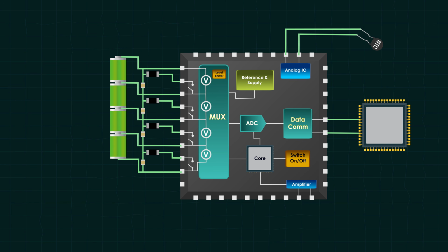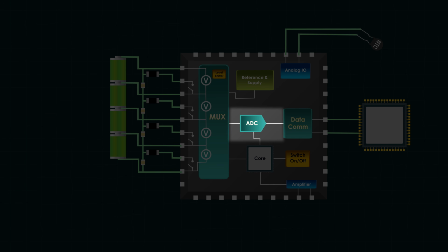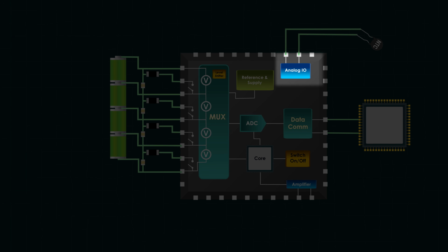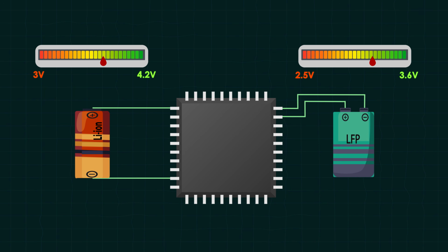In summary, the AFE is a mini analog measurement system. Multiplexers plus ADCs, precise reference, protection circuits, balancing circuit, and communications interface, all optimized to work together to give us accurate readings with minimal fuss. Pretty neat, right? And that's the beauty of an AFE. It's the silent guardian that keeps our battery pack in line by measuring, protecting, and balancing every cell so nothing blows up. In the next video, we'll uncover how to deal with different types of batteries and the practical design